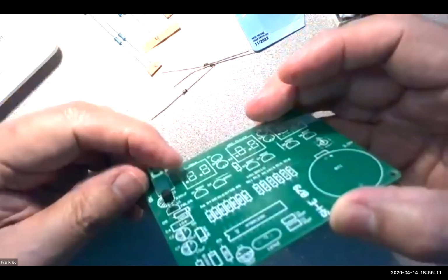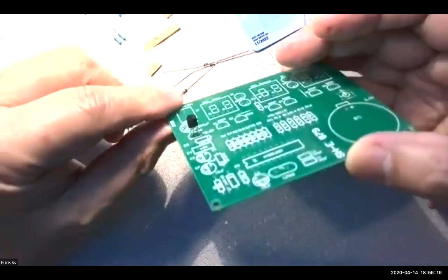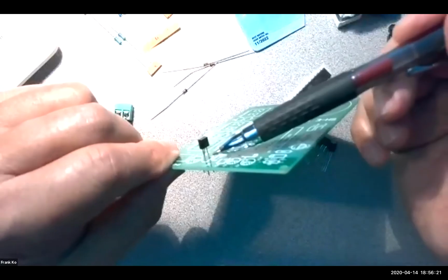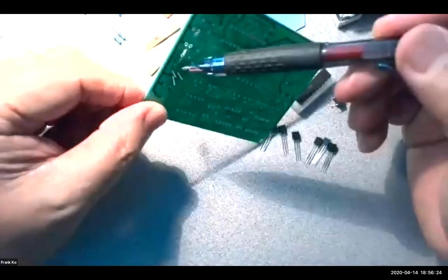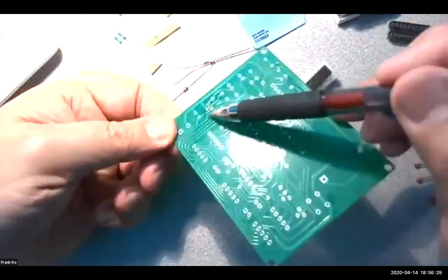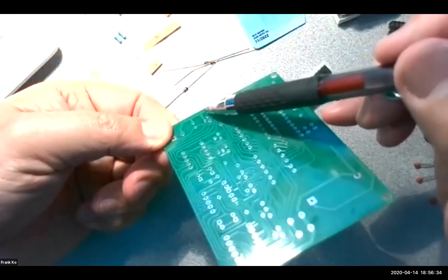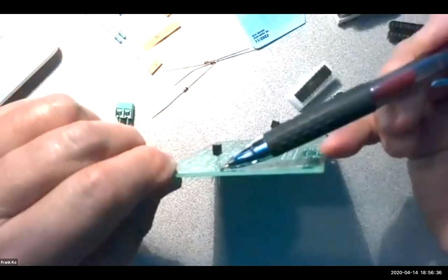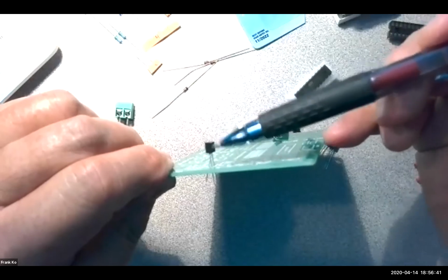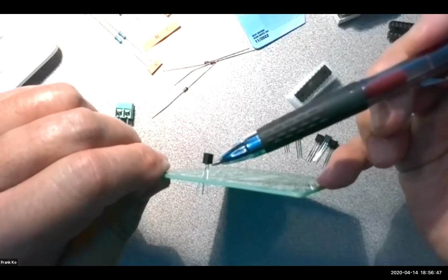A lot of students have taken these transistors and pushed them all the way down. I don't recommend that for several reasons, especially for a 7805, this is a 5-volt regulator. If you're putting heat on these pins back here to solder them onto the pads, that heat rising up that wire can go up into the chip and destroy the internal components of that chip. On these guys, it will be transistors. On this guy will be many transistors and other components.